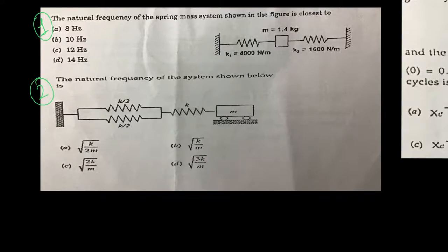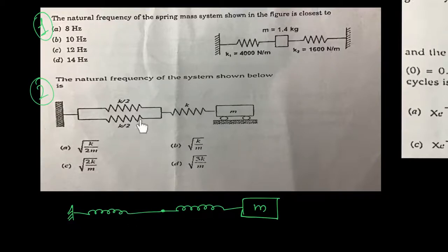So similar to what we have learned in electrical circuits, I'm planning to replace this particular spring system with two springs initially. So this is the first configuration, where I have two springs, and this particular spring is a substitute or a replacement for the two springs that we can see over here, which essentially means that this single spring should have the net effective stiffness of these two springs.